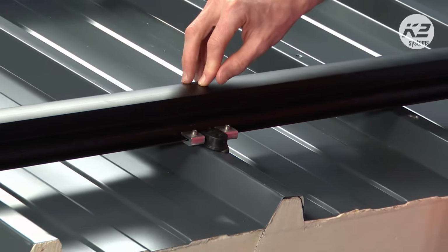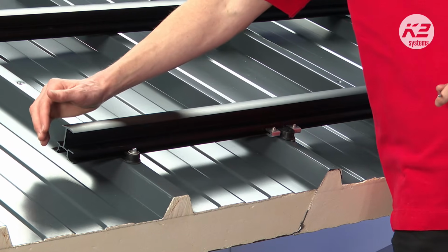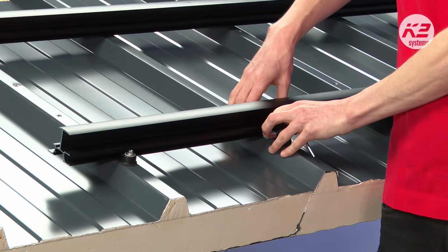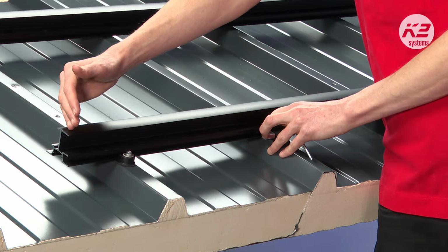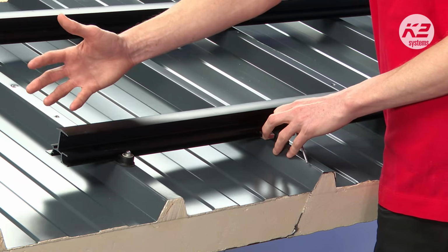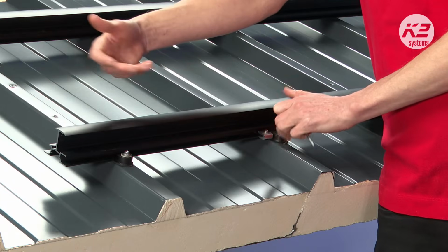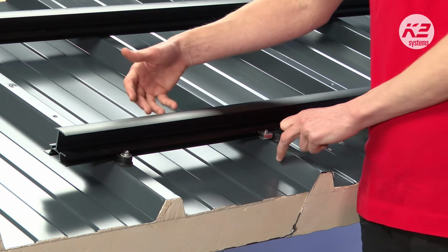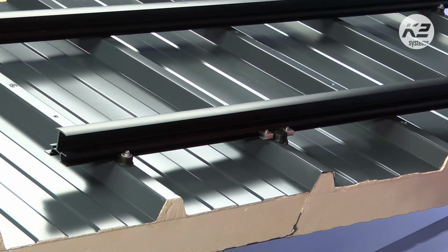It still allows the rail to expand a little bit heading out. However, this is okay because it's still fixed here. So the expansion out should then, if it does cool overnight, for example, or at a colder month, come back in a little bit. And again, we're only talking millimeters here, so it's not a huge issue, but over time, this topic can degrade the roof, and to avoid that, we have this fixing that we can put in here.